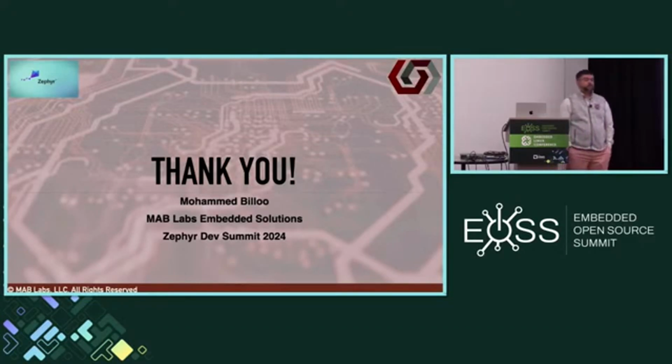So now you're booting the R core from the A core. You played around with the master function, so you first start Zephyr and then Zephyr starts your Linux kernel. So you have like a 1 second boot. That's a good point, but where would the Linux firmware and RFS be resident? It would be resident in Flash, right? And then you would have to instruct the Cortex-A somehow. I guess I don't follow.